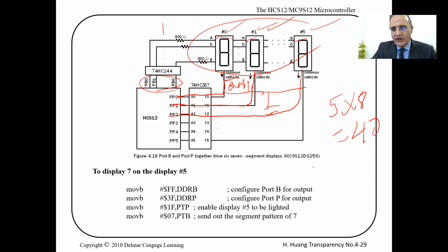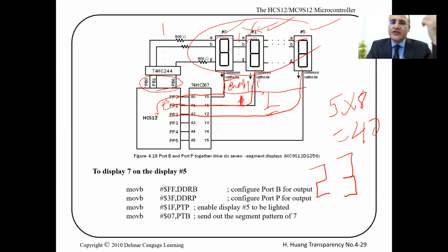So in this case, if I want to show the number 23 on 2 7-segment displays, I can connect this to ground, which means I enable it, right? And connect this to high, so it is disabled. So if you write a 1 and a 1, the LED will not turn on. So the whole 7-segment display is turned off.